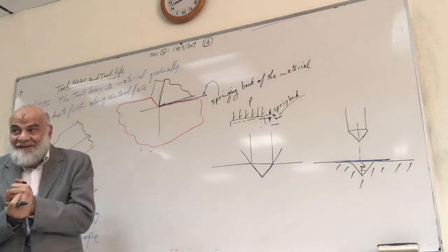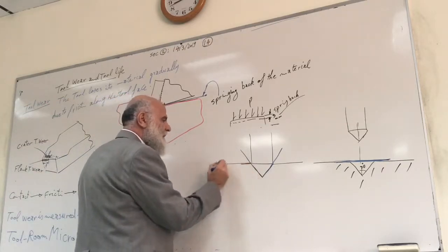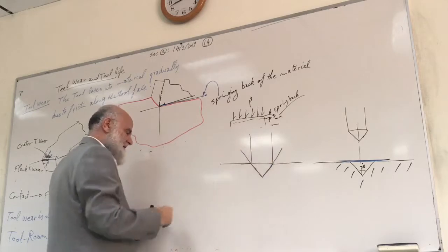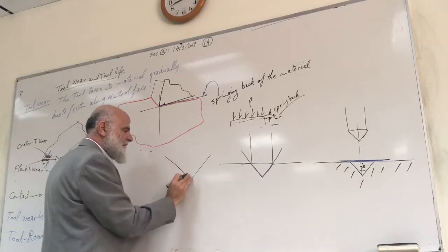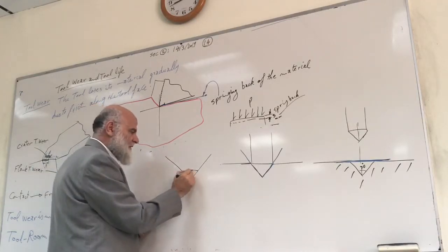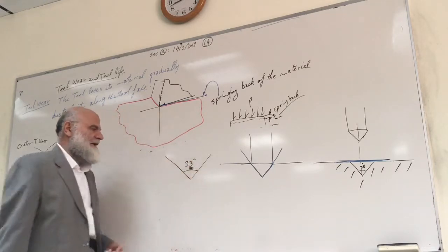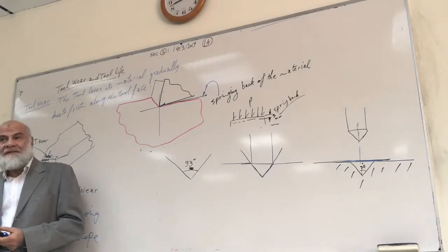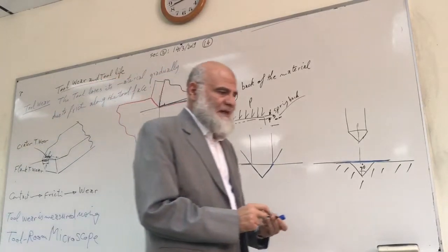Okay. But if I take the sheet out, I remove the punch, I take the sheet out, then measure the angle. How many will I find? Increase. I will find it 92, 92, 93, something like this. What are the 3 degrees extra? From where? Springing back. Elasticity, yes, but we call it deflection, also called springing back. Okay, this is a clear example of the steel springing back.